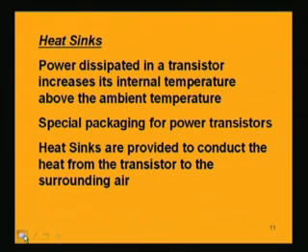Now we have seen that the transistor used in a power amplifier handles high power, so what happens is that it increases the internal temperature or the junction temperature of the device, and it should not be above the specified limit, with the ambient temperature specified as 25 degree centigrade.